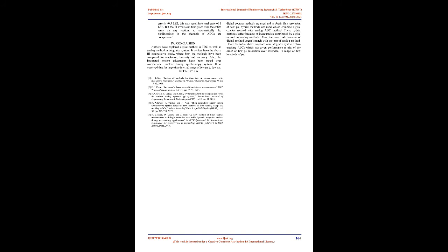In the analog method, if the ramp slope changes because of temperature drift in resistor and capacitor values, since the same ramp is provided to the input of both the ADCs, the effect will be cancelled out in TI measurement. E, conversion and digitization nonlinearity. The TDC method makes use of counter ICs to count time period T2. Digital counter ICs have proved to be precise and the TI measurement would be accurate except for the jitter of ±τ, where τ is the basic clock period. This jitter can be minimized by using the averaging method, as explained earlier in B.